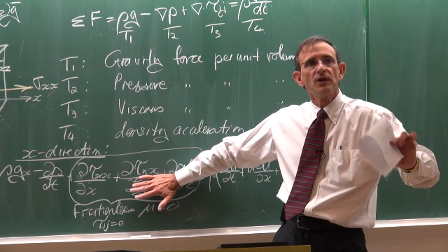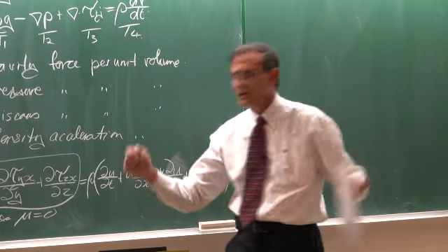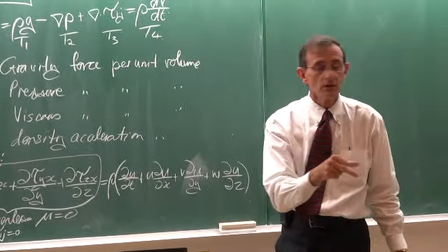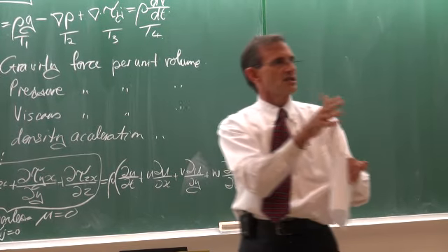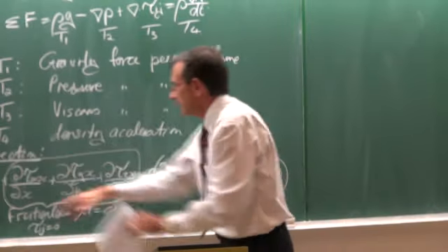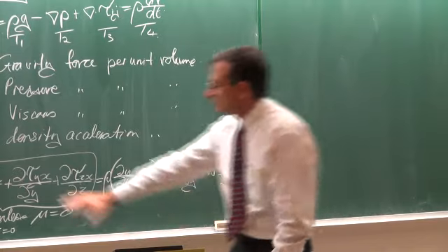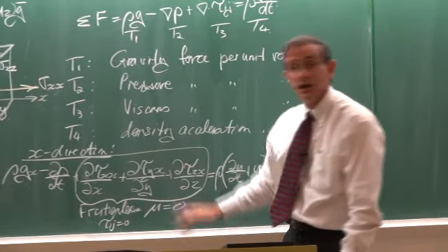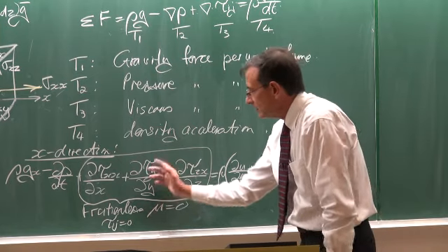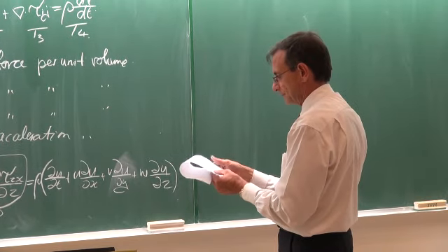The Bernoulli equation has about the most assumptions of any equation in fluid mechanics: viscosity is 0, density is constant, one-dimensional, irrotational, steady state, etc. But firstly, if you say that is equal to 0, which is a valid assumption for many cases, then you will end up with what we call the Euler equation.